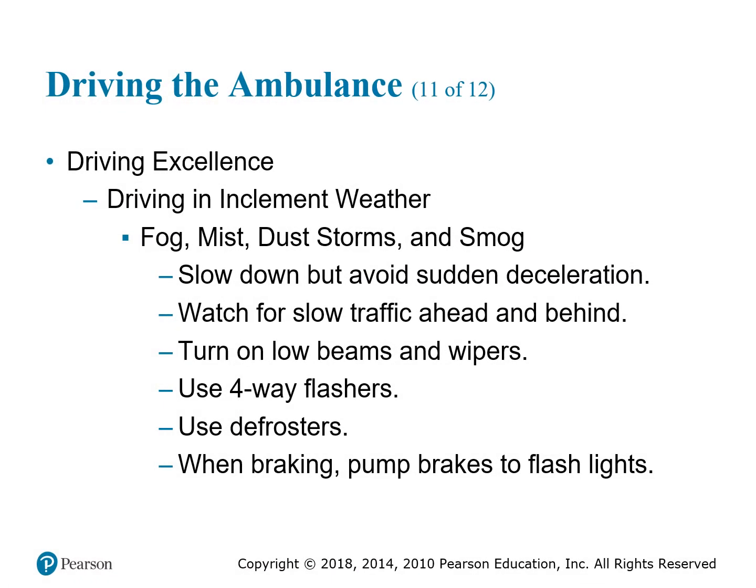When it comes to fog, mist, dust storms, and smog, slow down but avoid sudden decelerations. Watch for slow traffic ahead and behind. Turn on low beams and wipers. Use four-way flashers. Use defrosters. And when braking, pump the brakes to flash the lights so people can see.